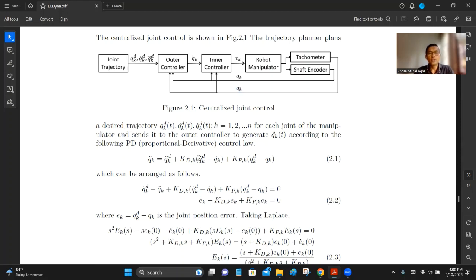So you calculate the difference, this error, and multiply by a gain, to give some priority or make it a stronger or weaker contributor in the equation. For every joint, you have a different gain. Okay, it's not the same gain for every joint. So that's why the gain is also joint dependent. So it is KD, K, right? You have studied proportional derivative integral controllers. You will immediately understand this is the velocity error. Therefore, the gain that comes in front of that is the derivative gain, okay?